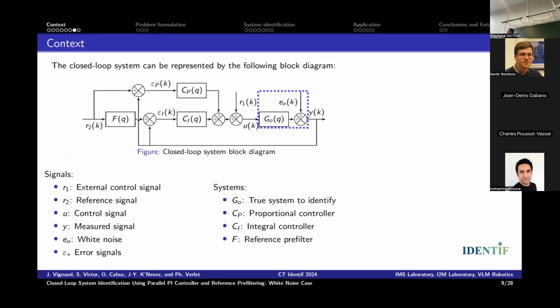Yeah, okay. So my question is, have you compared it with the output error approach, which is the minimal variance approach for that type of problems? Not really. I didn't try with just an output error. Yeah. Because the least squares supposes that your noise model is 1 over the denominator of your G. And so there it's not good. Then, well, even in open loop you're screwed with an ARX model.